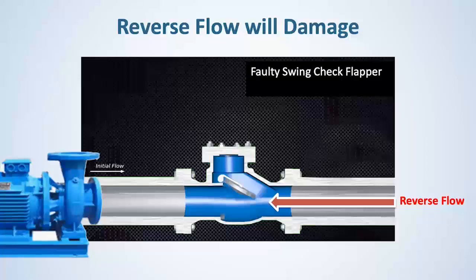For instance, reverse flows can cause the pump impellers to spin in the opposite direction. This can cause them to become unthreaded and disconnected from the impeller shaft. Other defects associated with reverse flow include impeller galling, casing damage, and accelerated wear of thrust bearings as well as the mechanical seals. The damage caused by reverse flows into pumps and compressors can cost hundreds if not thousands of dollars and lead to very inconvenient downtime and reduced productivity.